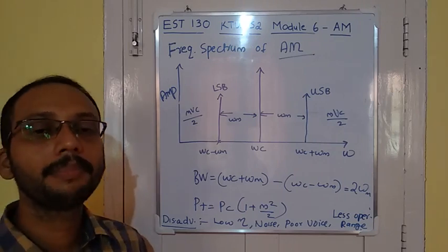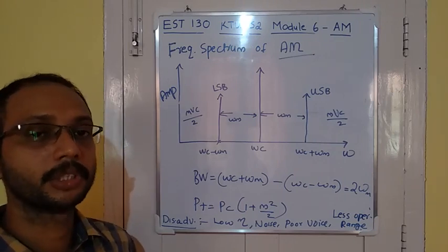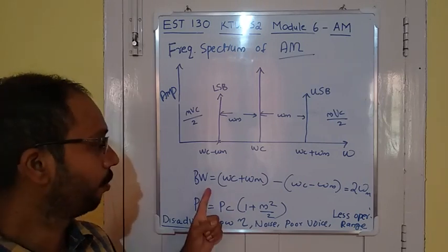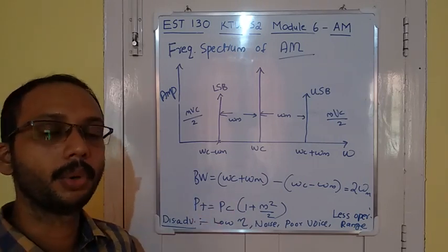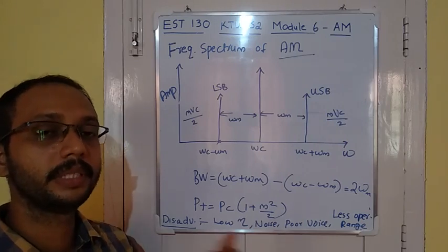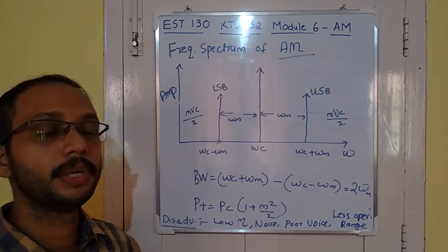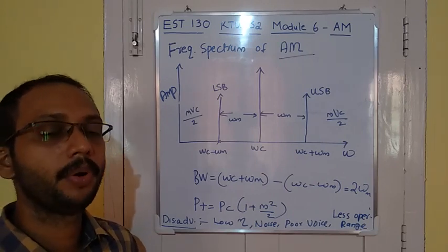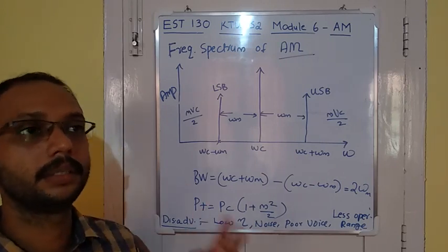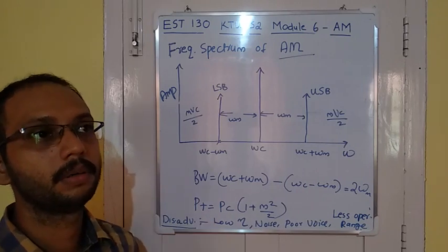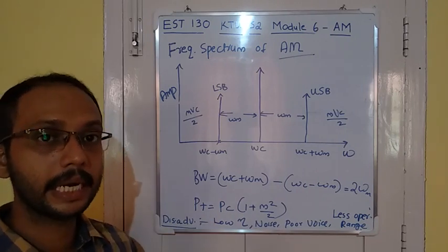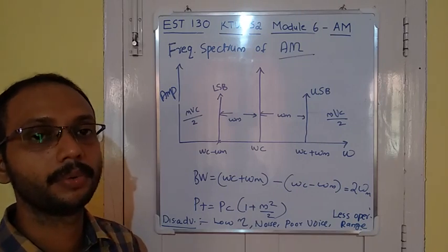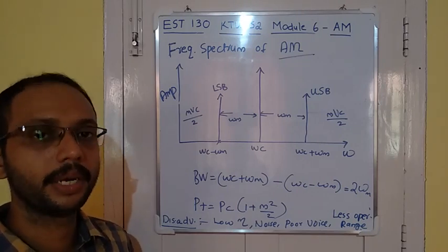In the RC coupled amplifier and its frequency response, we have calculated the equation for bandwidth. So bandwidth is equal to the frequency difference. From the 3 dB point, we have taken 2 points, lower cutoff frequency and upper cutoff frequency. So upper cutoff frequency minus lower cutoff frequency gives the bandwidth.